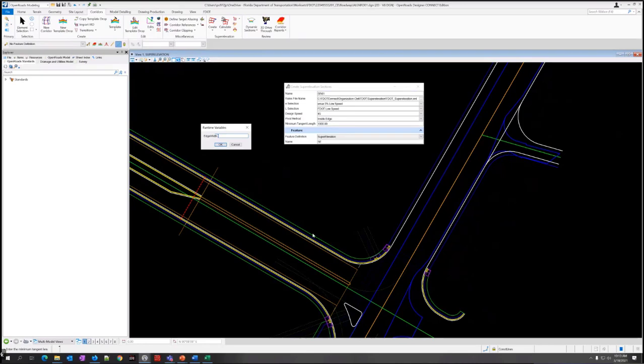So this is the width of the super elevation area. It's basically pavement edge to pavement edge. The only time it would vary is if you're doing a high-speed roadway, like the high-speed divided, where the way the super elevation is set, it only depends on each lane. So then it would just be the pavement edge to pavement edge for that one lane. But for all the low-speed ones, it's going to be the pavement edge to pavement edge from the outside of the roadway across the whole roadway, including the medians, all of that. So it's 80 feet is the dimension for this.